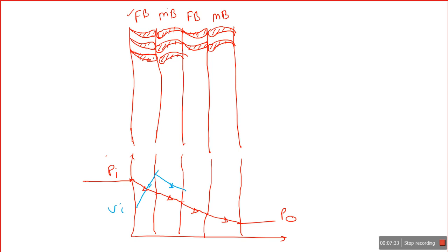Again that steam flows over the fixed blade, it acts as a nozzle. So in a nozzle there's a drop in pressure and an increase in velocity. That high kinetic energy steam again moves through the moving blade, there is a drop in its kinetic energy, and this is the outlet velocity.